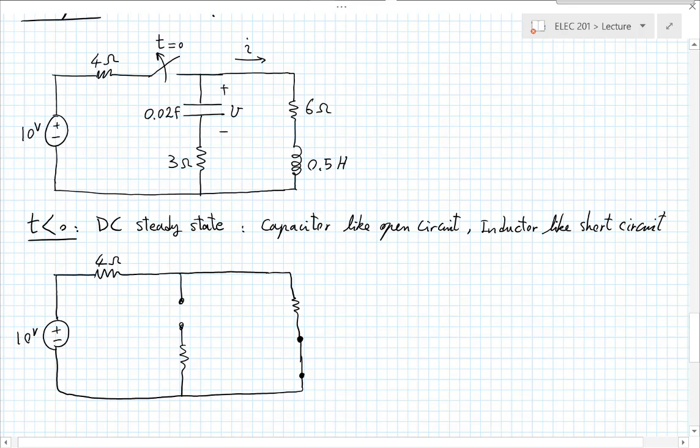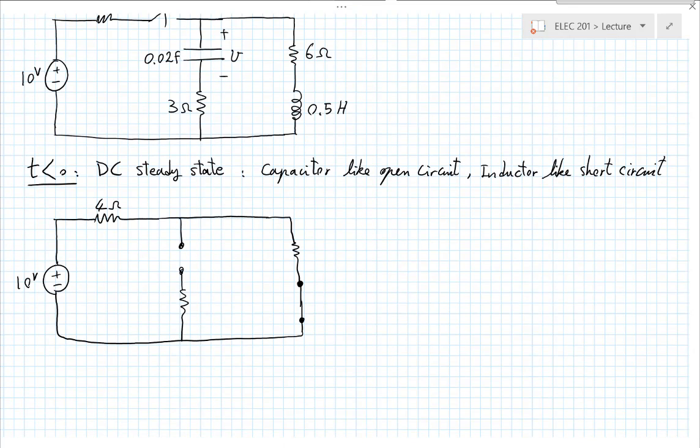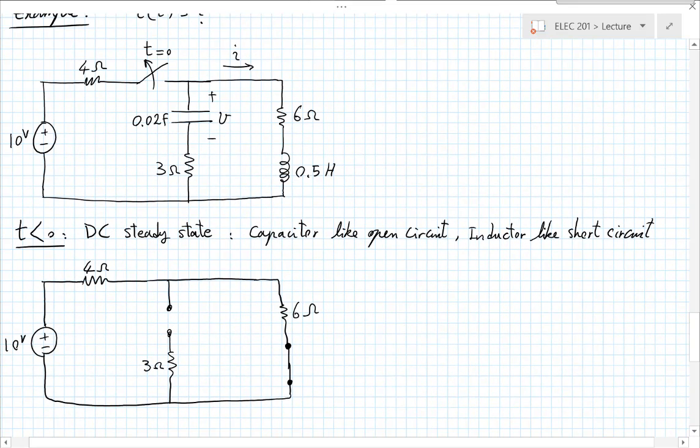Okay. And we have the values of these resistances, 3 ohms here and 6 ohms here. So now this is a pretty simple circuit to solve, I hope, because this middle branch is actually disconnected. So there's no current going through it. And if you wanted the current that we had called I up here,